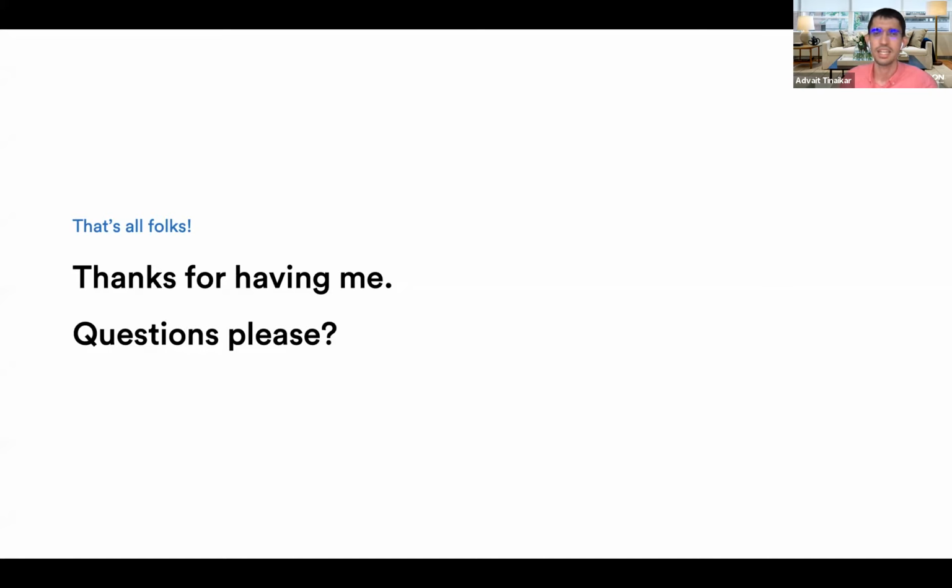We had like a site that was set up in the office to mimic about 100 to 200 lights in the ceiling. And what we did in the app specifically was there were a couple of things. Initially we actually had a range meter to show how far a particular light is. So as you're walking around, you can see a light dropping out. We also had the ability to let a user actually adjust what the range of lights that they want. So for example, if you're standing in a spot, you don't want 100 lights being found nearby, you want only 20. So the app could find the nearest 20 lights, and at times that helped in solving the interference issue.